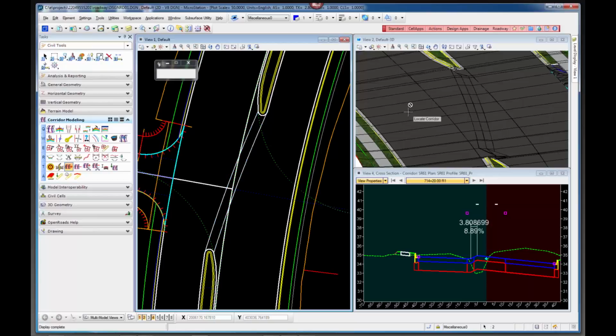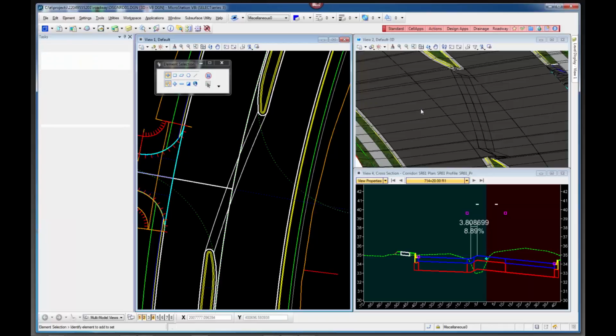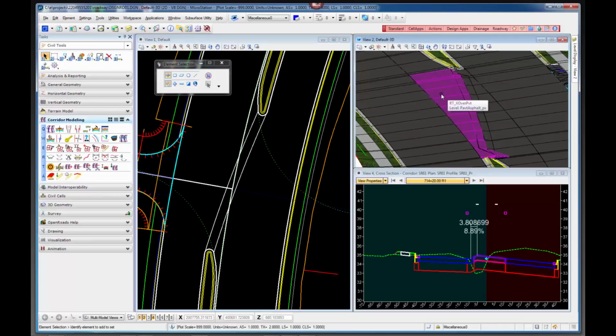And now you see that the pavement is rotating itself up. You can see this is the 2% slope up on one side, and in this location it's actually in the curvature, so obviously the superelevation is being applied forward and backwards there.